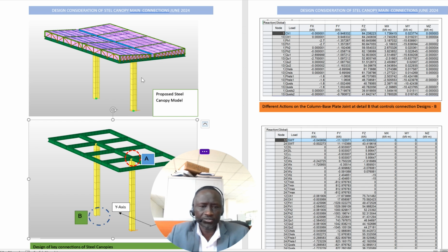If you do the vertical loads, the live load and dead load, I think that would be okay. But once it's subjected to wind, then you get into problems. So basically this one, I just wanted to demonstrate to you, based on the other demonstration of forces acting on the canopies, that key to those forces, you need to mark out the critical areas.